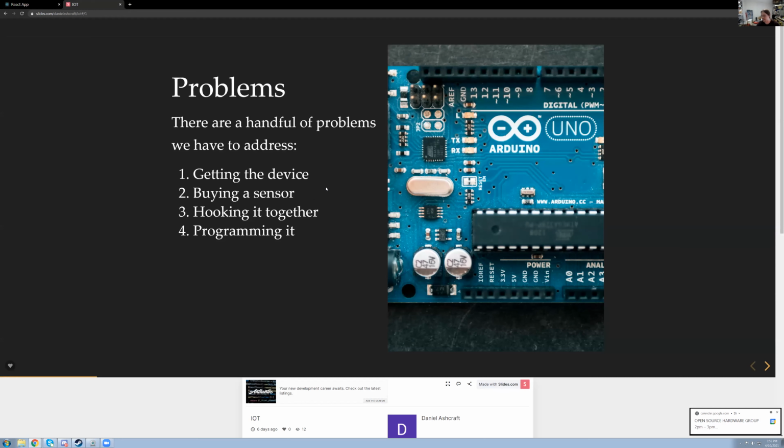You want to make it as easy to reconfigure them as possible. And I think that's where ESP Home comes in, because it's really easy to reconfigure those. You can even reconfigure them over the air, which is really handy. And because it's an open standard, if you brick it, there's a process in place for recovering those.